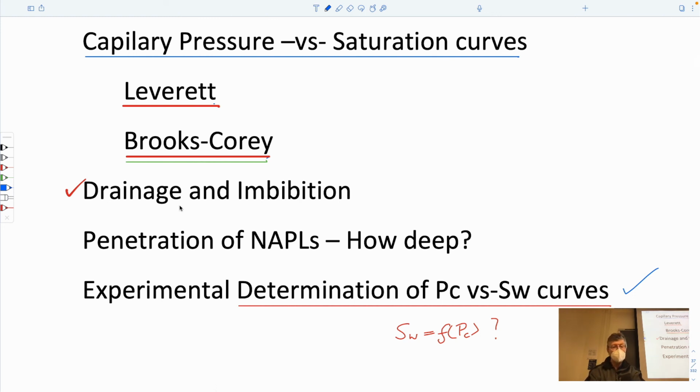So I think the thing we'll talk about next time is how we might use some of this information to say exactly what amount of supernatant fluid we can have sitting on top of these capillary barrier lenses. Because that's important in being able to figure out exactly what the architecture of the subsurface is in terms of this layer cake geometry that we've seen in these other idealized pictures. So we're still talking about how quickly the fluid gets in the first couple of months. It goes in there as quickly as it can. It gets held by capillary forces and then cannot move.